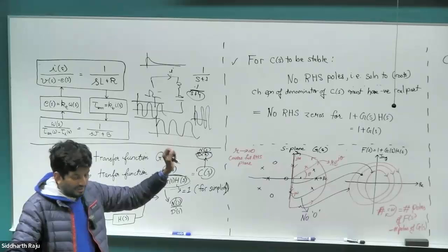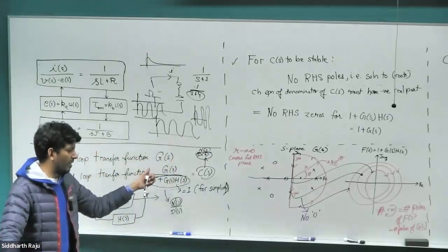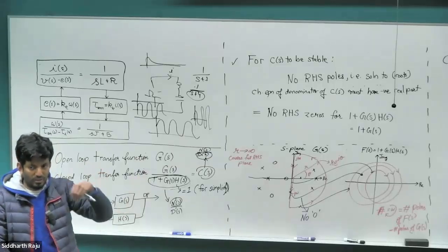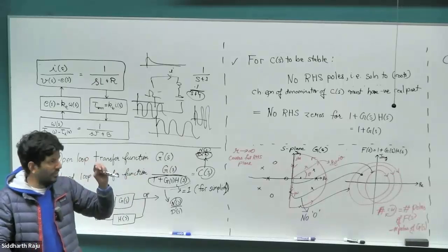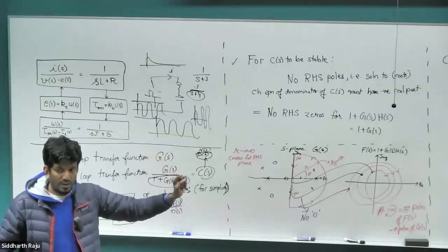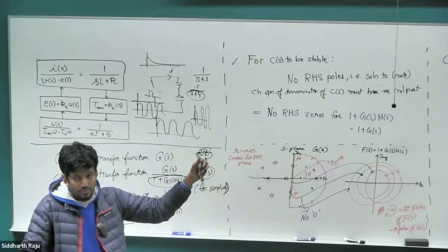Okay. Right? But in reality, when you do any kind of drive system or something, this will not just be a simple gain. You would have some kind of low pass filter. Because whatever current you measure, voltage you measure, they would carry the switching noises and all of those. You want to filter those out, and they would have their own phase delay and everything. So the H of S is quite critical. We can't ignore it in any way. Right? But factoring for the roots of H of S is very simple though, because it will typically be a low pass filter, which is omega by S plus omega.